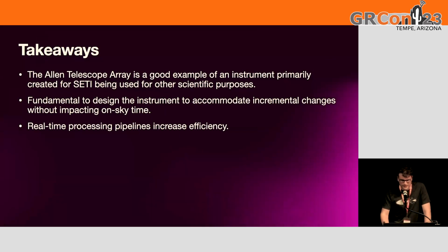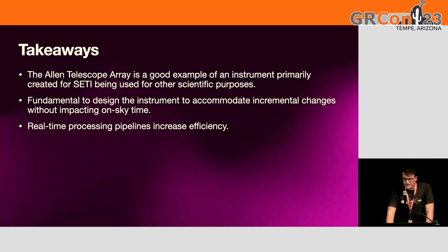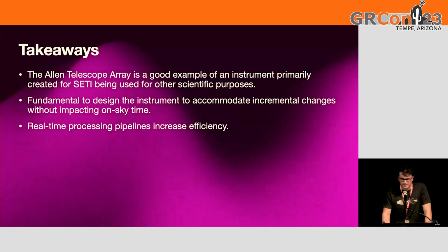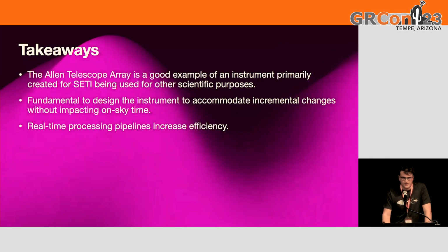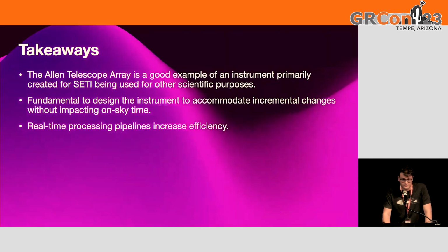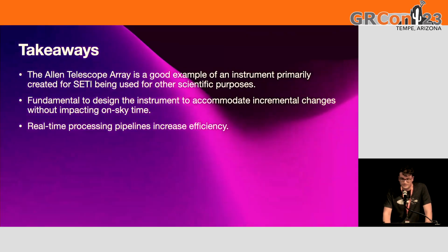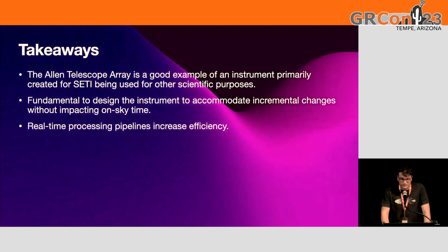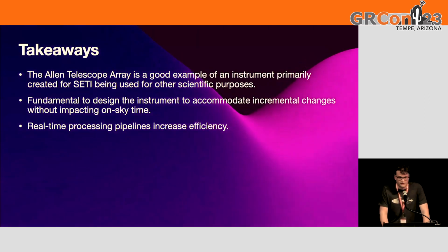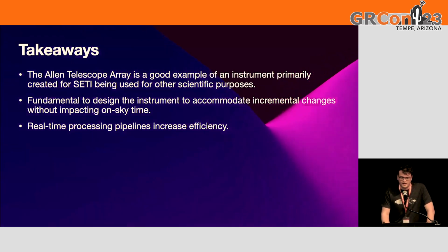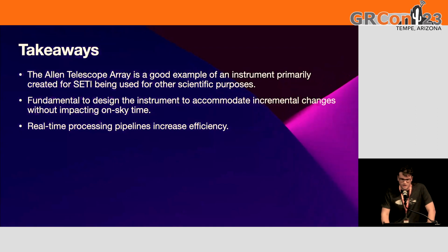So a real-time process can give you more abilities. For example, if you need to observe something for a long amount of time, and you can't because you're limited by the storage size, you can use the beamformer with the integrator that will time integrate your observation and run that in real time for as long as you want.